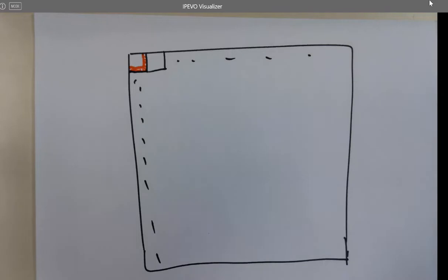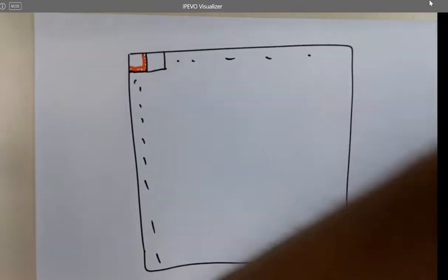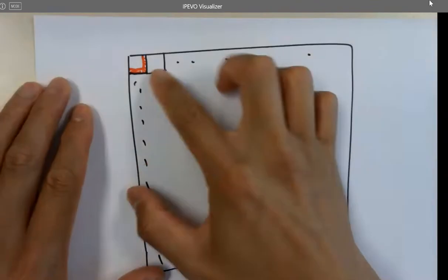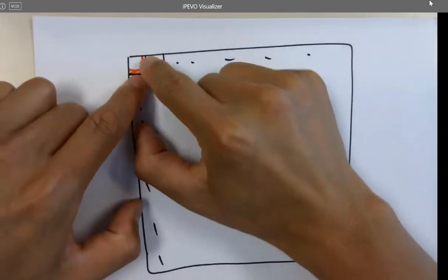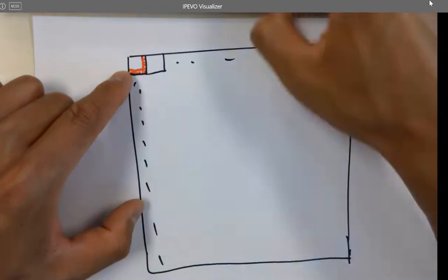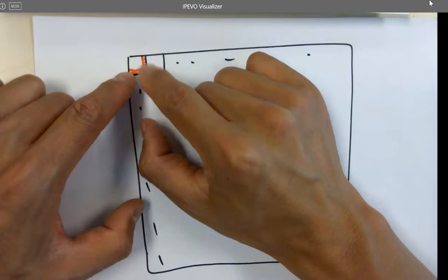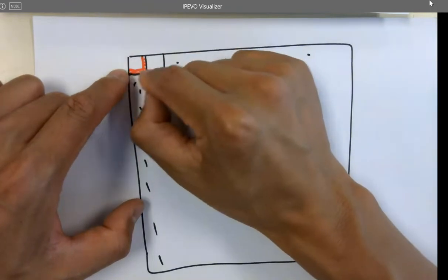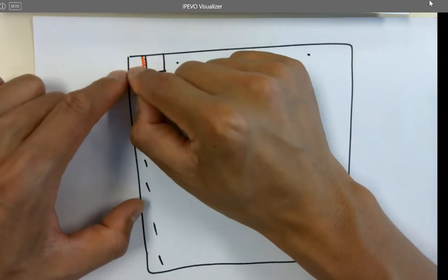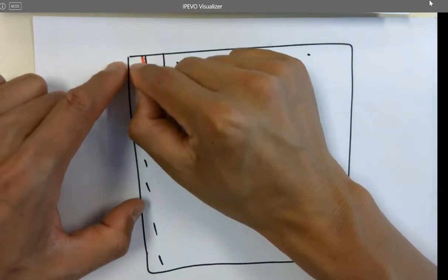It's an opening on the chip, and you have lenses in front of it to focus the image, make an image in front of the photo sensor. Right? It's just many photons hitting that image sensor, trying to make an image. If a lot of areas are irrelevant, for example the caps, switches, which are not sensing photons, the photons are going to hit these areas and not get sensed. So the quality of the image will be bad. So you need the photodiode area to be a little bit bigger.